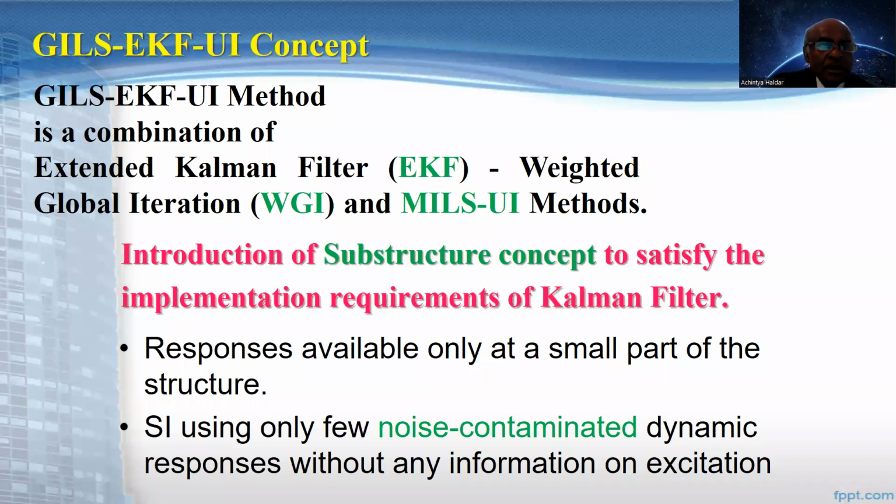And what we did, we proposed extended Kalman filter. It would consider the mildly nonlinear response with weighted global iteration and iteratively least squares method. And to do this, we have to introduce what we call the substructure concept.